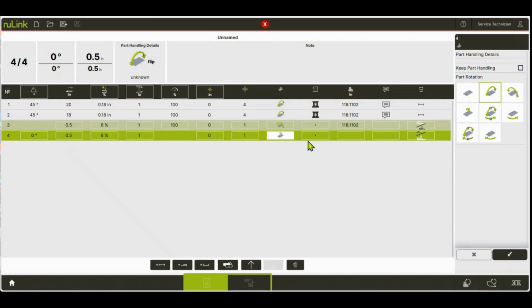If we're going to smash the hem, same tool. Material table at this point doesn't really matter because you're not bending anything, because material table has angle compensations. When you're smashing a hem, angle compensations don't really mean anything to you, so they are just not populated.